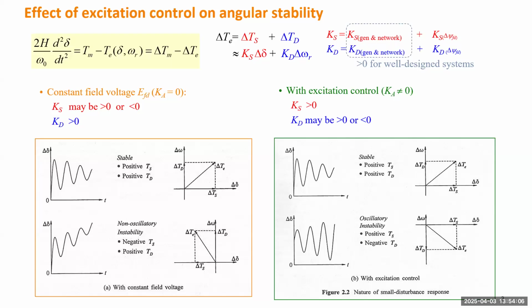If you simulate a very large system, and there's some disturbance, and you see many generators become stable and a few generators become unstable, if you see any generator behave like this one, what does that mean? That generator has very weak excitation control. If you want to make that generator more stable, you need to try increasing the gain. If you are allowed to adjust the model, that will definitely be better and will bring this generator more stability.